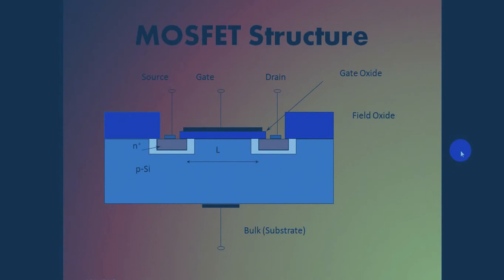Before discussing the structure of the MOSFET, I would like to tell you what a MOSFET is. It is the most commonly used field effect transistor in both digital and analog circuits. It uses a channel of P or N-type semiconductor, named P-MOSFET and N-MOSFET respectively. Silicon is the main choice of semiconductor. However, silicon germanium is used by some common chip manufacturers. Some other commonly used semiconductors such as gallium arsenide are not useful in MOSFETs because they do not